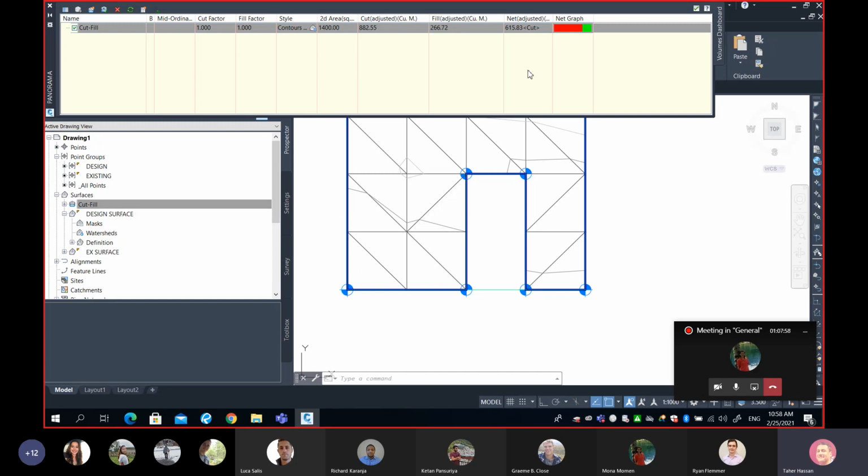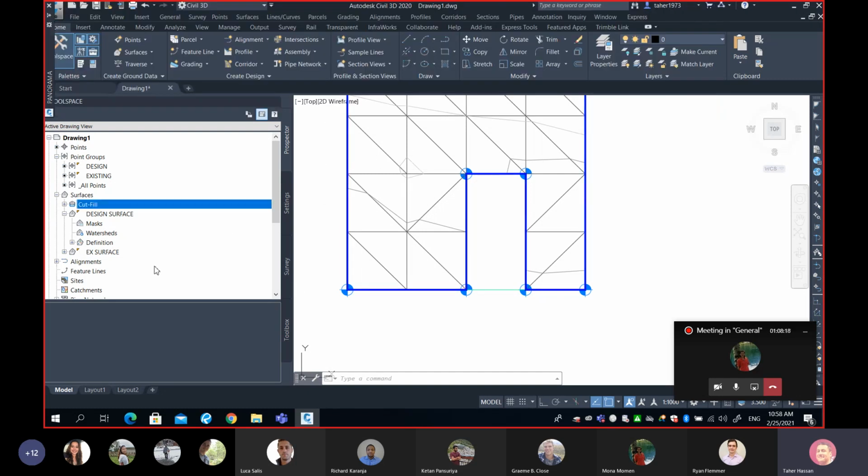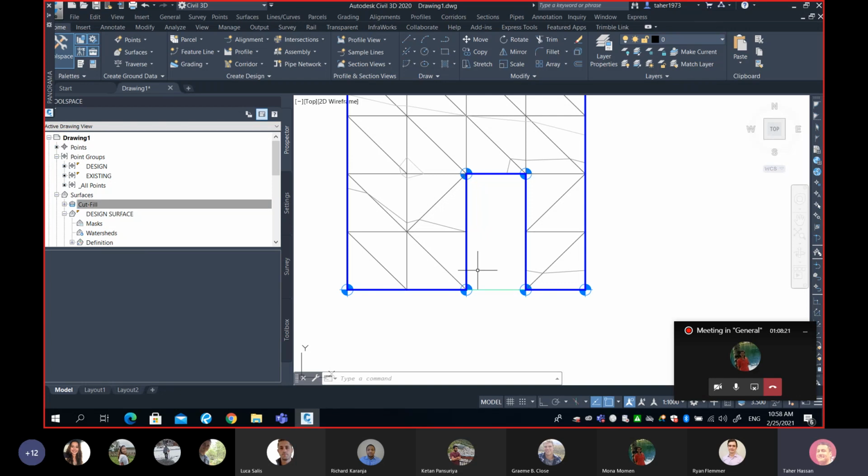The good news is when we do something, the software dynamically updates the volume surface, and you don't have to repeat the process. If I change one of the components, the software will automatically update the numbers. Okay, watch this please. For example, let's say I change my mind, I want to go back to 9. Anybody to help me to do that without doing undo? This time put -2 to decrease the elevation. You can do that for sure. You can simply go to and choose your design and drop it down by 2 meters.